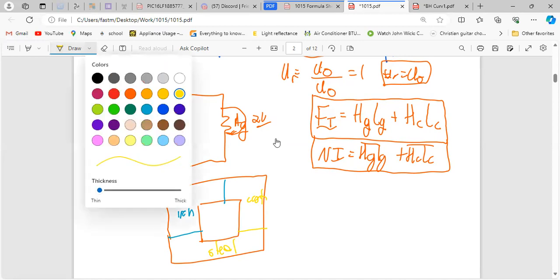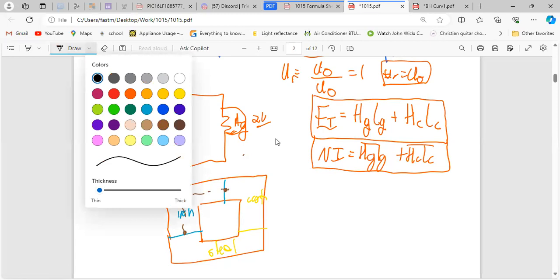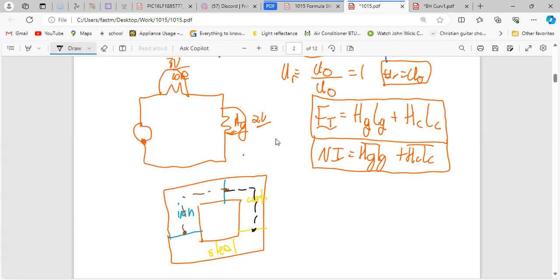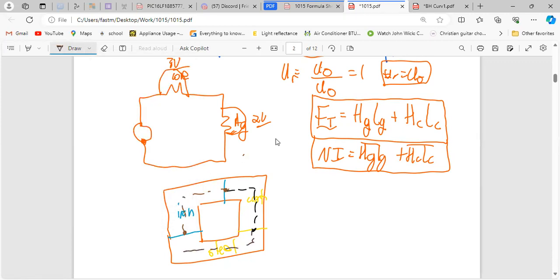So you can't apply Ampere's circuital law flat out. Why? Because you have different materials. So you have a core part here, a next core part on the next side, and then a next core part from here to here. So you have three lengths, L1, L2, L3.